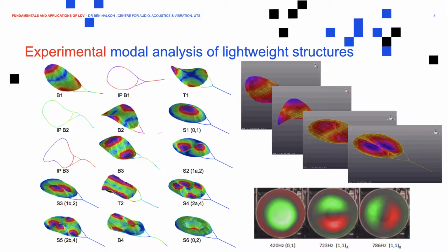No, these are done sequentially. So we survey the target of interest over a series of individual measurements. There are multiple point vibrometer systems becoming available, up to 48 channels, but this is not a whole field measurement. It's a discrete measurement and it's built up. So there are some constraints around how we make that measurement, of course. We need to have stationary vibration that we can repeat from one measurement to the next, and typically we'll take multiple averages at each point to build up a survey of this type.